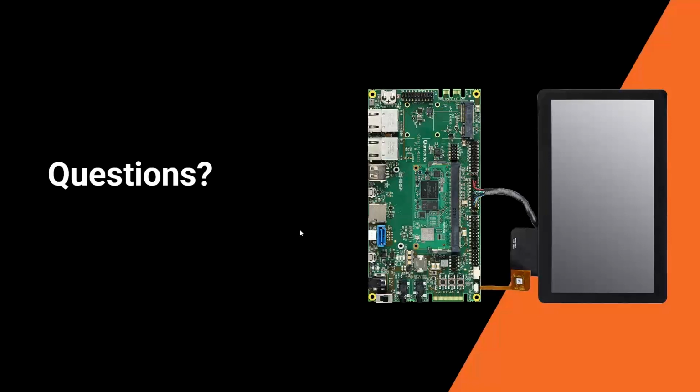On the Mini, differently from the 6UL, there is the support for the DRM and also for Wayland. That was part of the default implementation. We tested both the Wayland and the DRM. Honestly, the Wayland was working fine. The DRM backend, apparently, was slower than the FrameBuffer backend, but we did not investigate that much.